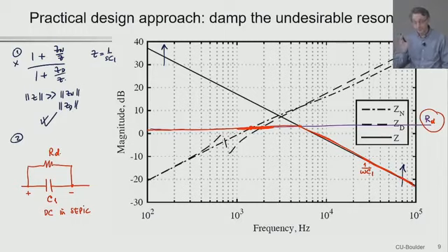So to mitigate that, we realize that all we need to have is a resistive impedance right here, but it doesn't matter what happens right here. And so we can add an element in series with RD to remove the DC power dissipation and preserve the resistive property of that impedance in the range of frequencies we care about.